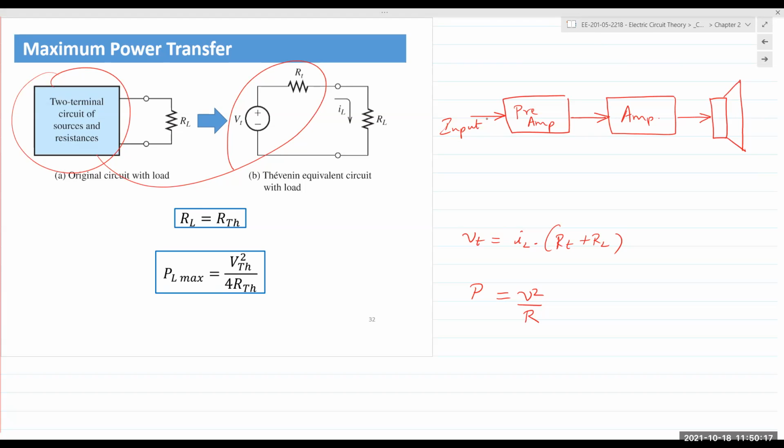In your book, there is also an example, and I like that example too. Has anyone ever lived in a cold climate? Like a snowstorm, ice storm, you try to start the car. It doesn't start very quickly if the battery is old. The reason is the car battery can be represented as a Thevenin voltage and has its own Thevenin resistance, right? In cold climates, the reaction, it's an electrochemical battery cell, right? So the reaction will take place a little bit slowly.